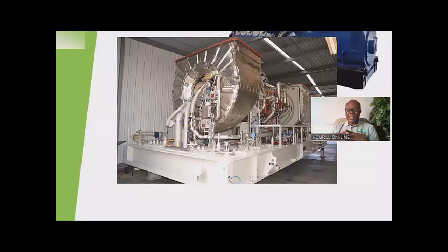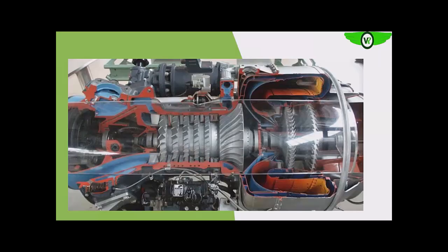So this compressed air is now sent to the combustor. At the combustor, fuel or gas is injected, and then the mixture of fuel and compressed air is ignited in that very combustor. Okay, so after ignition, the high energy combustion product is now directed through what is called the transition piece onto the turbine blade in the turbine section.